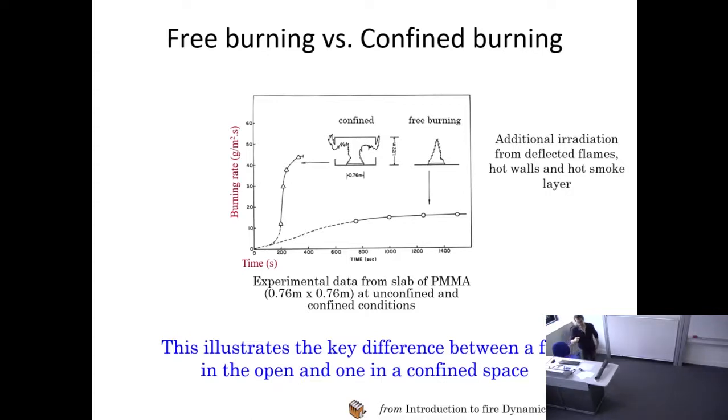Or the heat gains. What happens is that now the flame, instead of going conically away, every single location of the flame is releasing heat. Some of these burning sites are very far away from the fuel that is pyrolyzing, and some are very close. But when you have a ceiling, you force the flame to grow laterally, horizontally, and you are netly increasing the amount of radiation. You're creating a surface that before could not reach the fuel by radiation, but now can. So you significantly increase the amount of radiation from the flame to the fuel.